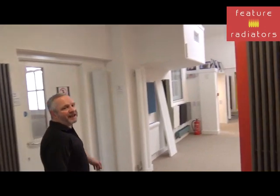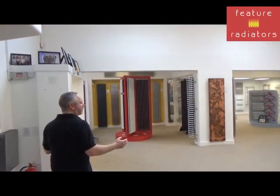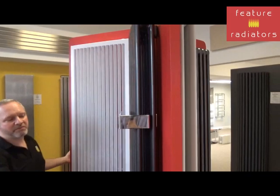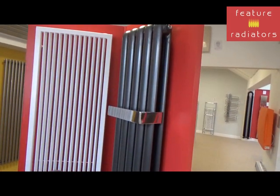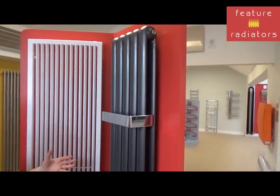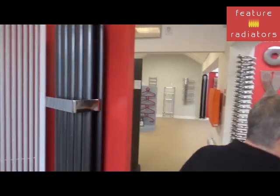So we calculated 1140 watts. If we look, for example, at this pod radiator, you can have the same radiator in different sizes. This one gives you 1944 watts, so it's quite a bit over the requirement. So what we could do is ask, is there a pod radiator at a different size to give you the right amount? So if we go over here,